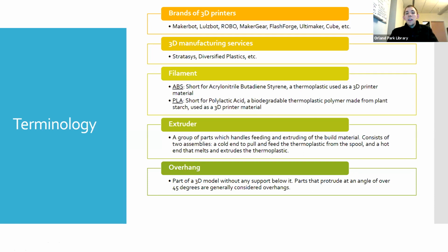So with PLA, since it's biodegradable, if you use a base and you need something that stands tall, and you want to remove the base of it so it prints correctly, you can throw it into something like hot water, and it'll degrade a part of it. So then you can get that piece off instead of having it stuck at the base.